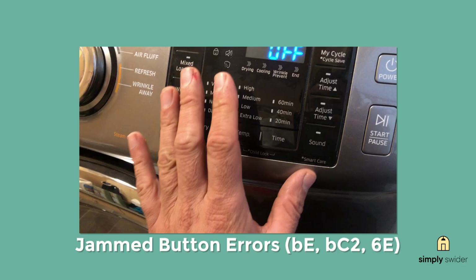Button errors happen when the control panel thinks one of the buttons is stuck down. You'll see B2, BC2, 6E, 6E2, or 6C2 when this happens. It's like the dryer thinks you're holding down a button even when you're not touching anything.